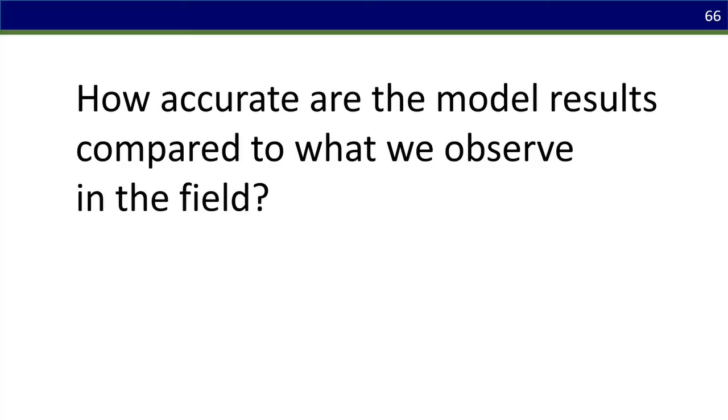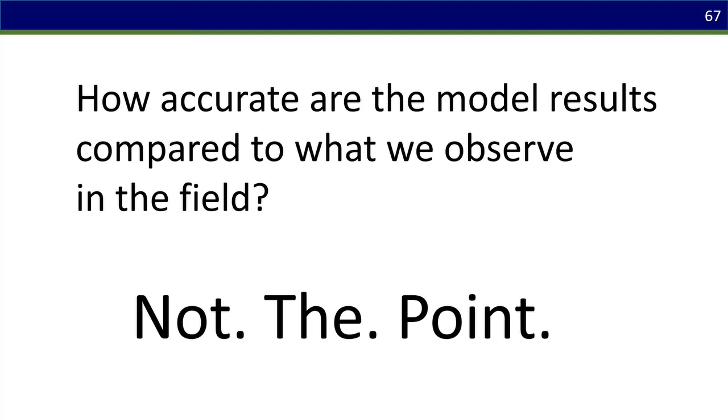That brings us to the big question, right? How accurate are these model results? How well do the model results compare to what we observe in the field? To me, that's really not the point. The point is less about calibrating the model to match field observations than it is for the modeling effort to be consistent, so that you can compare results from one culvert to the next, and you can compare peak flows from one location to the next. You can spend a lot of time and money trying to calibrate something.